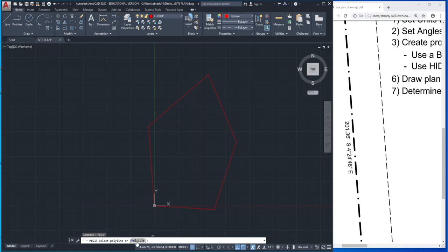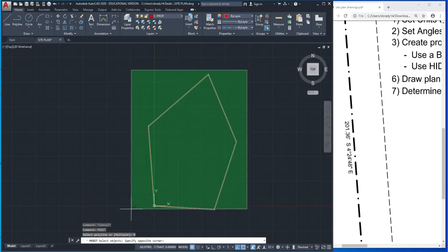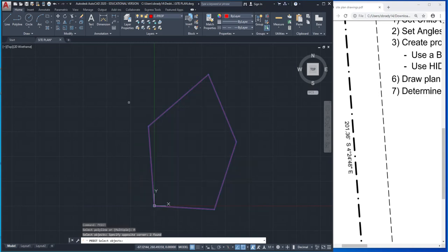If I can click on it, you'll also notice there's a blue letter, that M. Of course, I'm a keyboard person, so I could type M, enter, and get the same effect. I could click on multiple or type M, enter. Now I'm just going to select all these lines because I want to join them all together. When I'm done selecting, I hit enter one time, right?